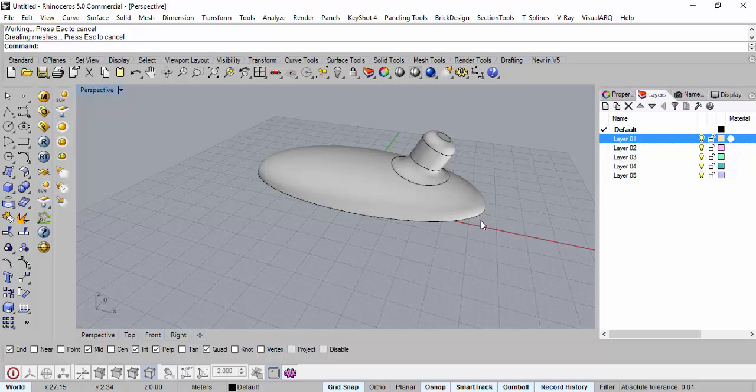You want me to repeat it? Draw the ellipsoid. Go in the plan, draw its size, then go in any of the other viewports and give it its height. Then in the front mode, any one of the elevation modes, you draw a line and cut away the lower part. Then you can use either a pyramid or a cone or a cylinder as an object. Draw it in plan, give it a height in the other viewports, rotate it conveniently, and move it along the ellipsoid, and then you can trim away each other using each other as a cutting edge and each other as a trimming object also. So there will be a two-step process.